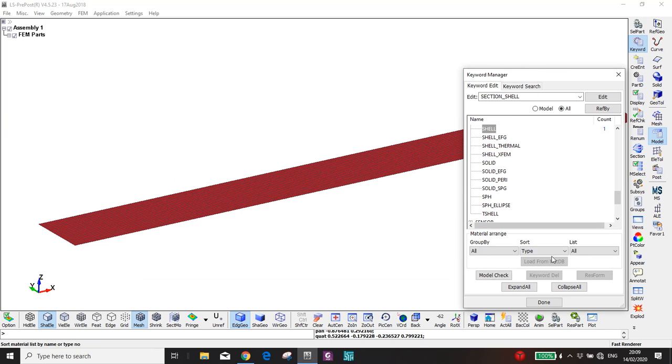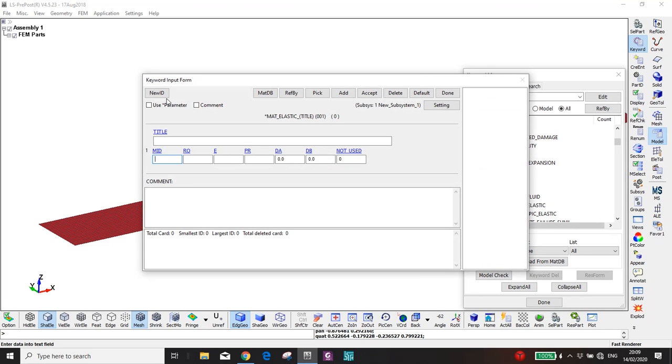Now after we do that, we go and define the material. Just take the basic elastic material model, should be fine. The density is 2400. In this tutorial I'm dealing with kilogram and meter. I'm not using millimeters as usual. So this one will be kilogram per meter cubed, and E will be 27.5 gigapascal, Poisson's ratio 0.3. These two actually are the material properties of concrete. Of course, for modeling concrete in different simulations you better use different material models, but for the time being, because we are just using modal analysis, this one should be fine. Okay, accept.